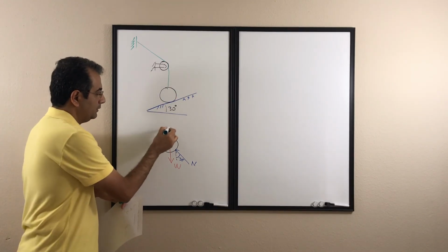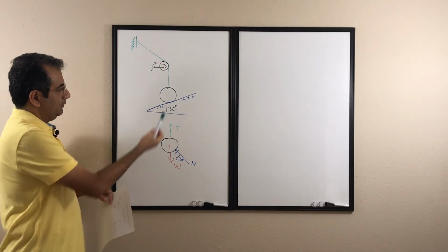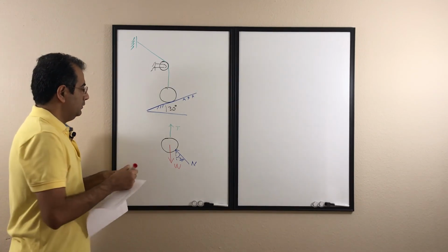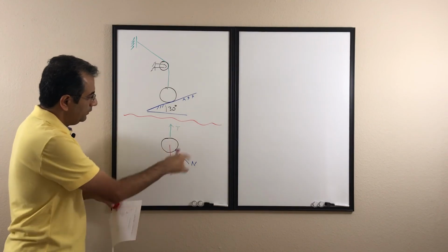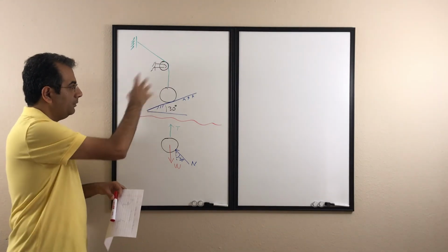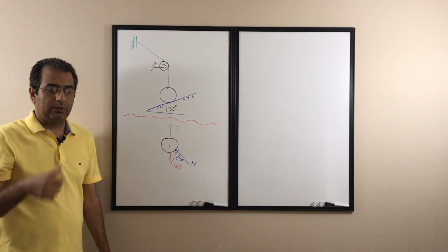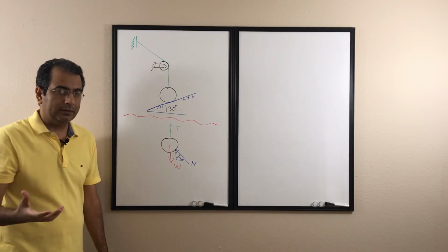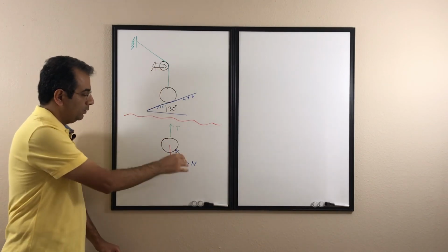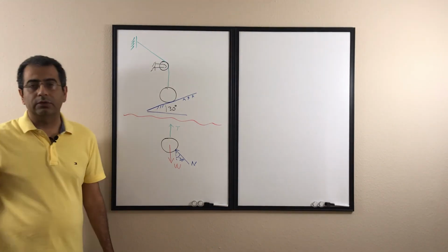That rope also holds it in place, so we have the tension in that rope. This is the object with all its supports, and this is going to be the free body diagram. This is the object itself. So the steps: we disconnect the object from anything that holds it in place, and then we put all the external forces on that object. Our external forces are the active forces, here the weight, the forces that want to make it move, and then the reactive forces, the forces that want to hold it in place, which here are the tension in the rope and the support by that surface. This is how we draw the free body diagram.